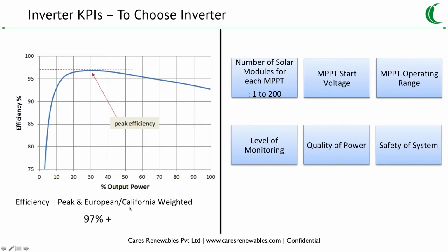a good inverter. And if you want to understand what this weighted efficiency is, I would recommend googling a bit on European and California weighted efficiency. Under Indian conditions, California weighted efficiency is a bit similar to the efficiency of the inverter. So I would recommend looking at this as a metric rather than the European weighted efficiency.